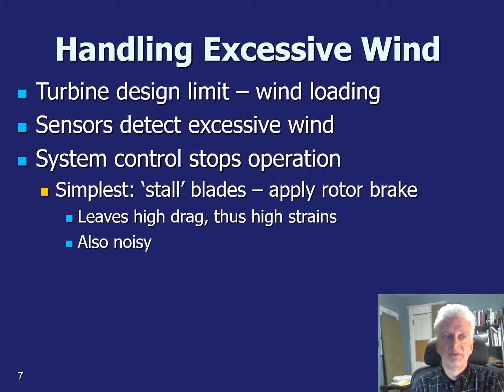They will have very high drag when they're prevented from rotating through the wind. This will put very high strains on the system, but they'll be static strains in the sense that because the system isn't rotating, it's not going through the same extremes as the blade passes through lower and higher heights. This is more prone to generating high noise.